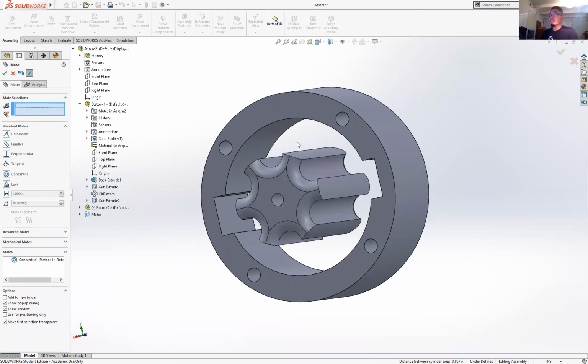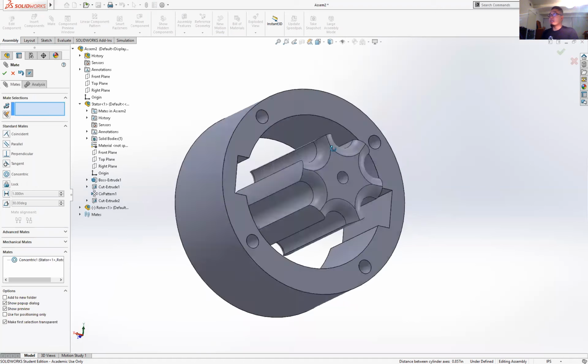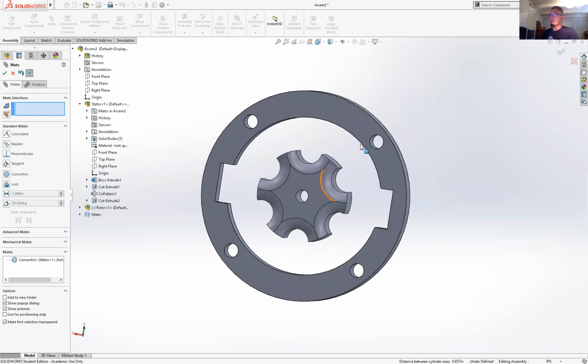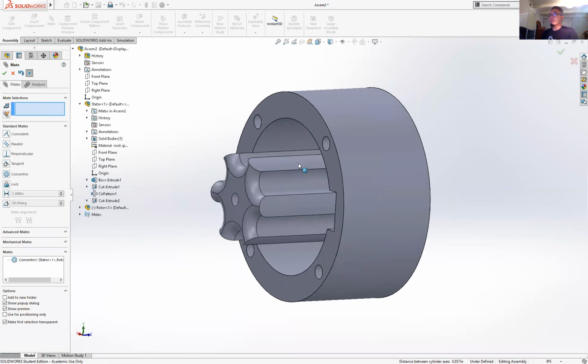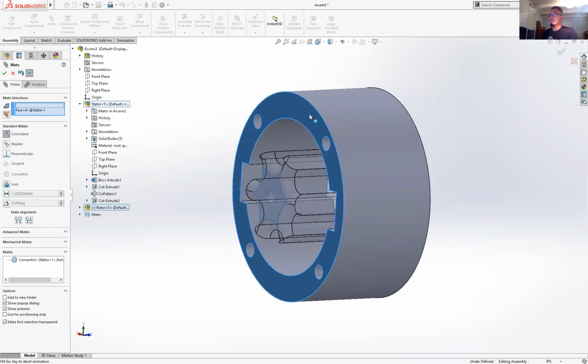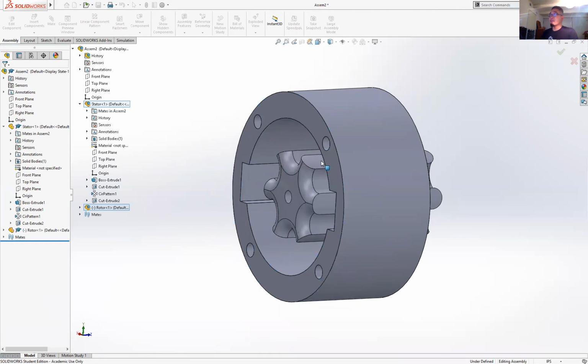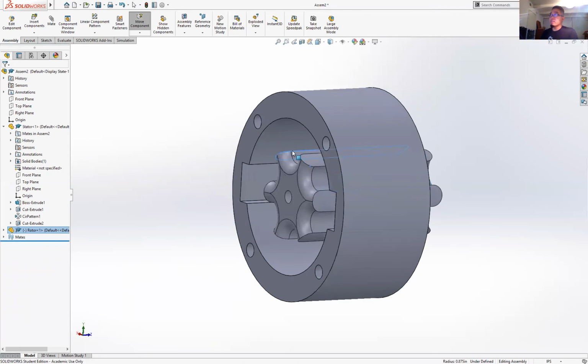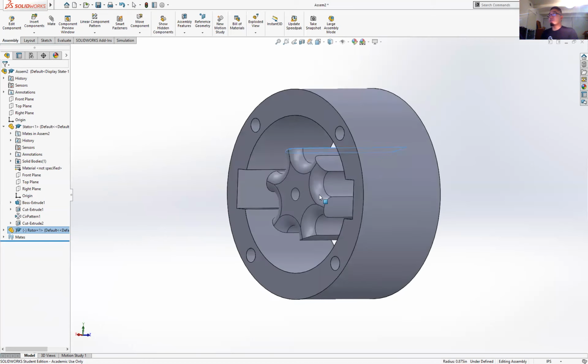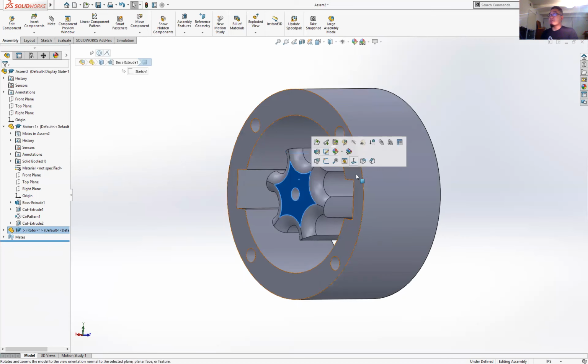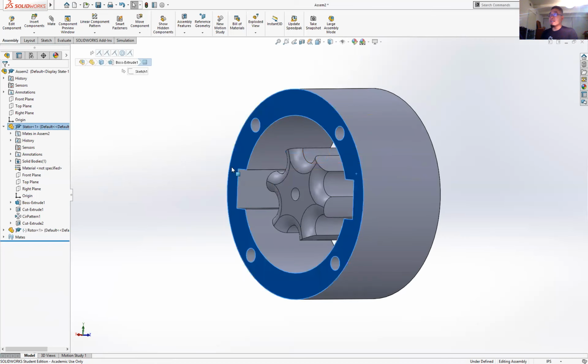So once I click that check, notice it will align the centers of both of these. Okay, let's say the other thing I want to do is align the edge of this face to the edge of this face. Bang. Okay, so I hit check, check, yay. And if I watch, I spin this, notice it stays constrained. It shows you the freedom of motion. Now, maybe in your assembly, you might not align this face to this face. That might not be a good idea, because if you put your end cap here, the wires wouldn't have any place to move.